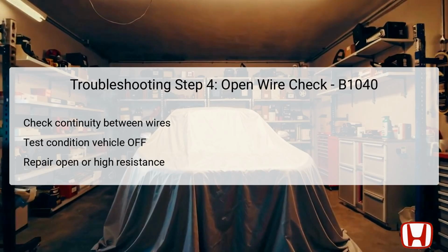If you detect battery voltage in this test, it signals a need to repair either an open or high resistance issue in the ground wire or the connection at point G351. However, if continuity is absent, that indicates an open or high resistance within the wire itself, which also requires immediate attention to restore proper communication.